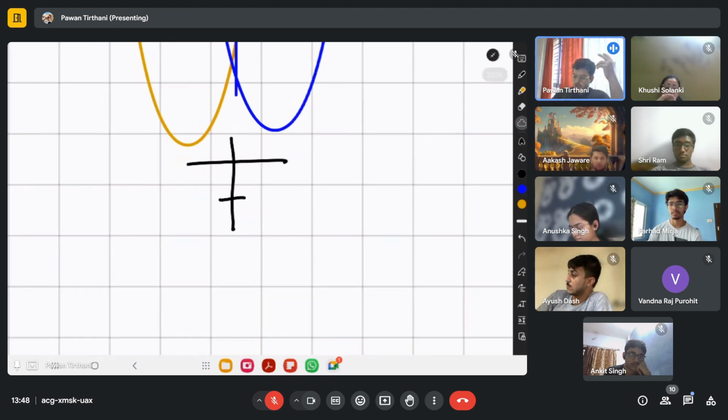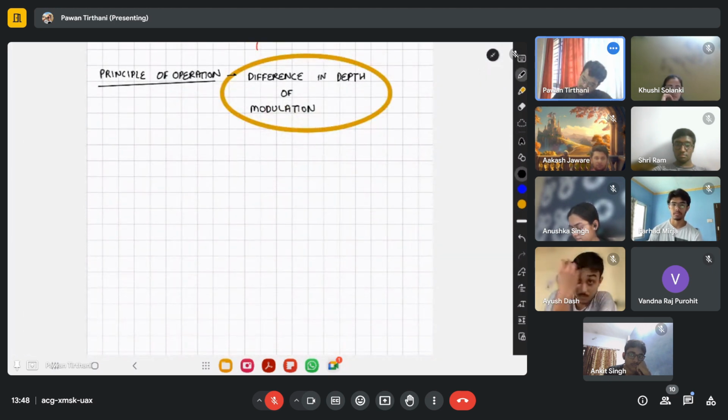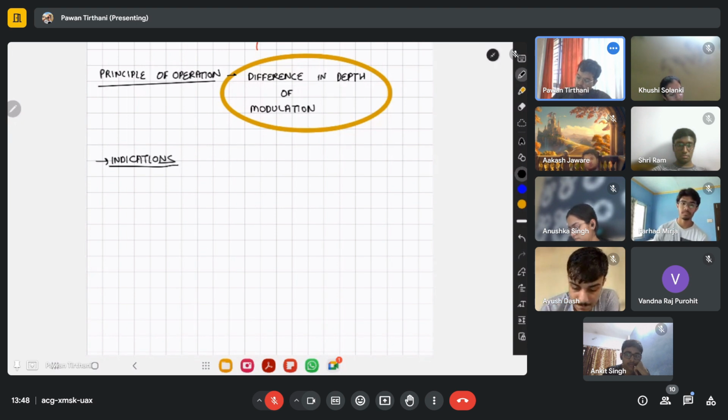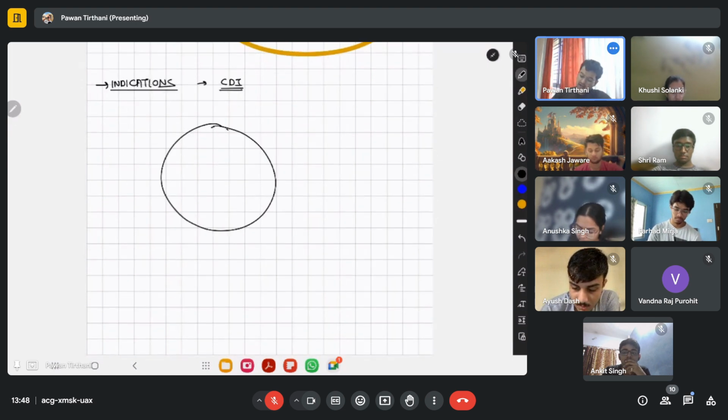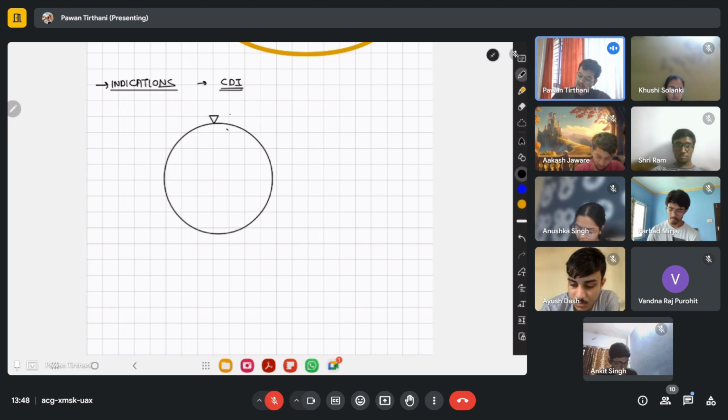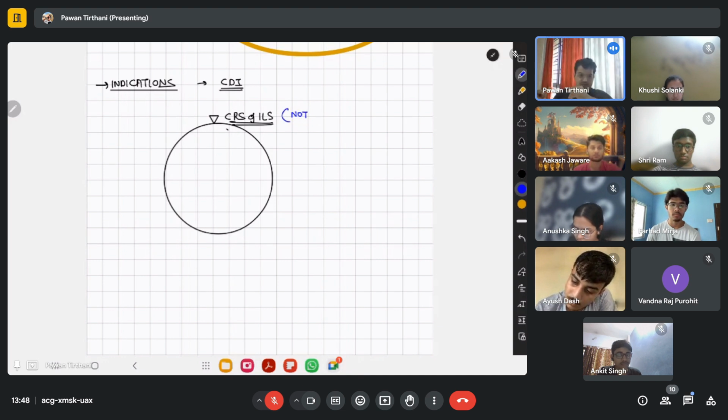How are the indications shown to the pilot? The indications that are shown to the pilot are on a CDI, also known as a course deviation indicator. Okay, similar to the CDI in VOR, here it is the same. You have selected the course of ILS on top. Now, you do not require to set the course of the ILS. In VOR you had to set the course, right?